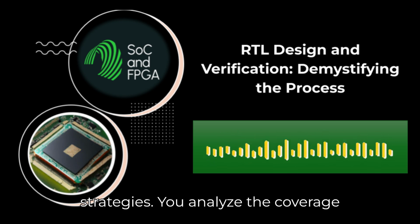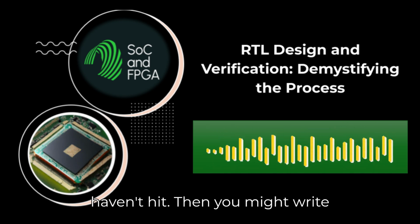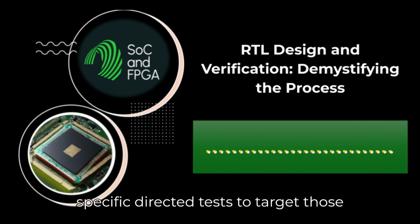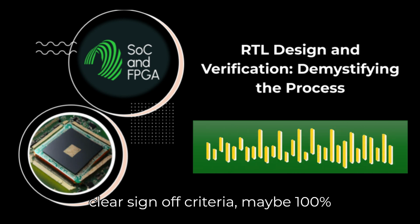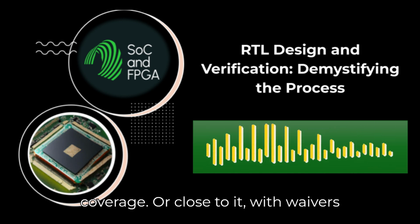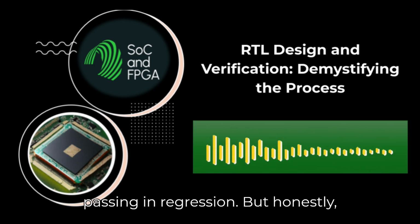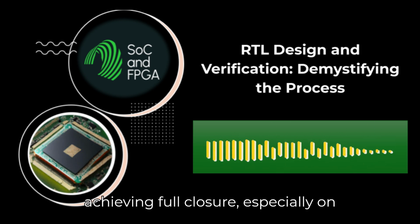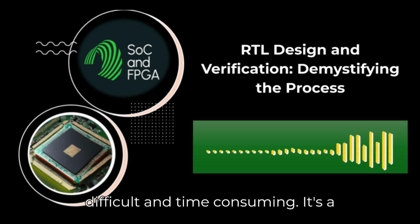You analyze the coverage reports to find the holes, the areas you haven't hit. Then you might write specific directed tests to target those difficult-to-reach corner cases. You set clear sign-off criteria, maybe 100% functional coverage, 100% code coverage, or close to it, with waivers for unreachable code, and all tests passing in regression. But honestly, achieving full closure, especially on complex designs, can be incredibly difficult and time-consuming.